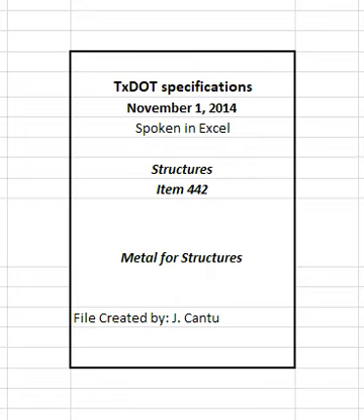The weight of castings will be computed from the dimensions shown on the approved shop drawings. Shoes will be measured by the weights shown on the plans. Weight of high-strength fasteners will be based on Table 6. Weight of other metal will be based on Table 7. Splices will be measured as follows. No additional weight will be allowed for weld metal in a welded splice. Where a bolted splice is permitted as an alternate for a welded splice, measurement will be made on the basis of a welded splice. Where a bolted splice is required, the weight of the splice material, bolt heads, washers, and nuts will be measured with no deduction for holes.